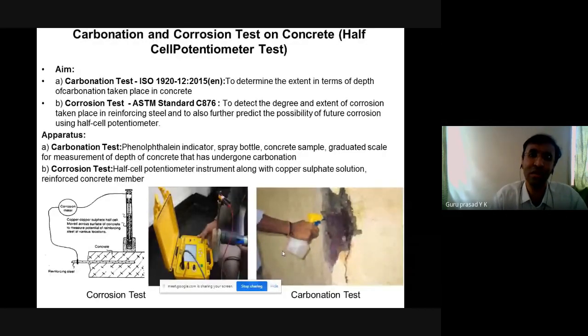If you apply compression load on a glass cylinder or glass cube, it breaks. Or if it is a cast iron cube or small cylinder, it just breaks instantaneously. That doesn't happen with concrete. Even after it attains the peak load, it slowly undergoes cracking and then crushes. So that is called quasi-brittle behavior.